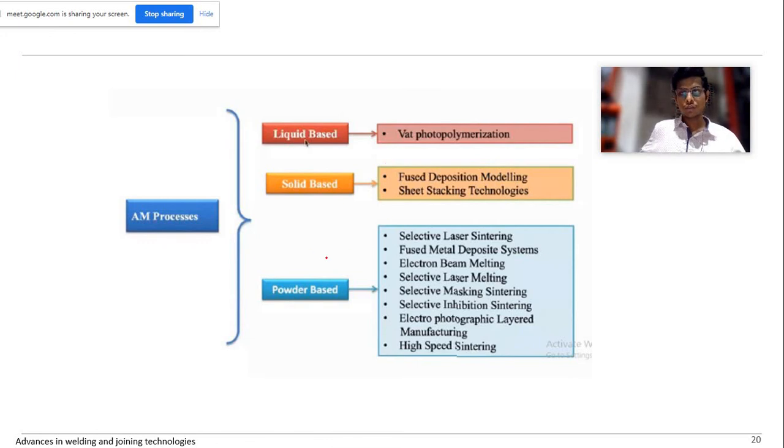Electron beam also is used to melt the powder or else some wire material to get the material. And also the other polymer based processes are there, fused deposition modeling, even vat polymerization, liquid. Here the material will be liquid based on the heat. Here the liquid will be cooled and it will turn into a solid, and we will get the 3D component from the CAD. I don't know whether I am complicating things or not. I just wanted to give a few insights about this process also.